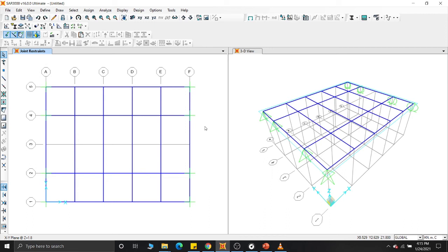And then the other main point is the load application. Ideally, we should consider the dead loads, the live loads that are coming from whatever the carpet of the road and of the pedestrians and all that, and especially the moving loads, where you have to consider the HHB loading and the knife edge loading.